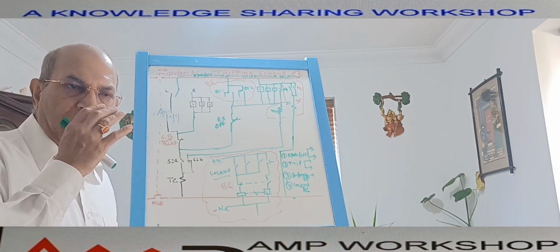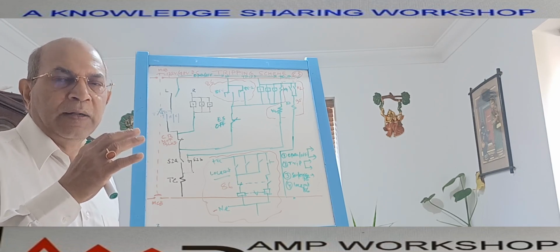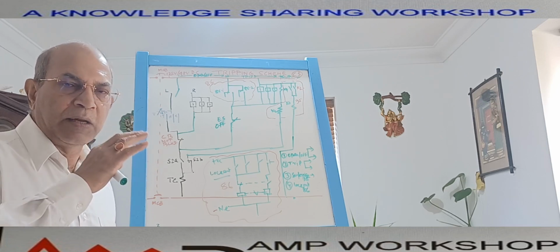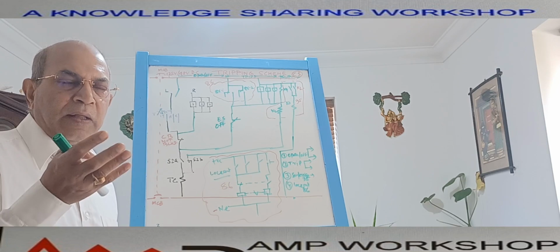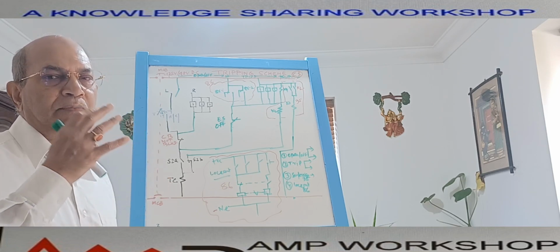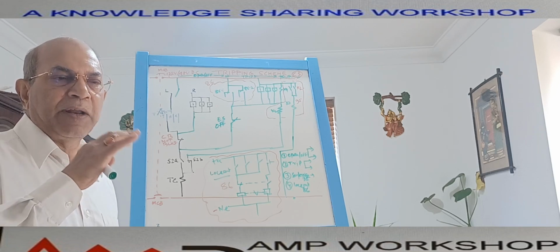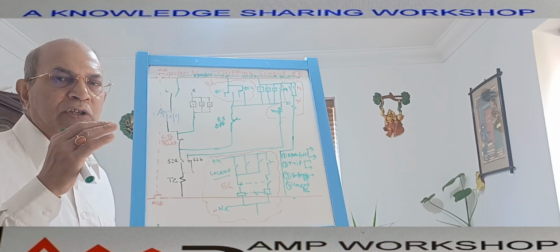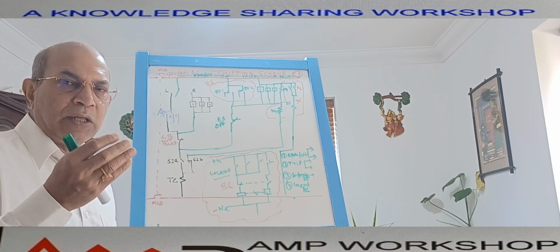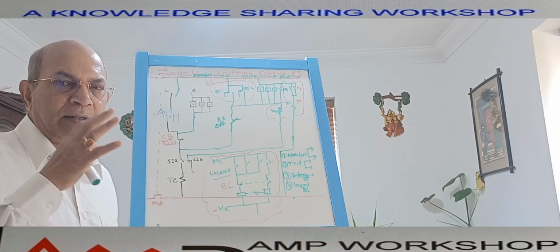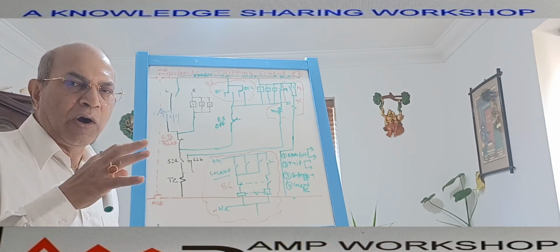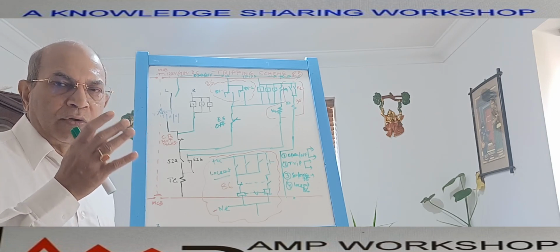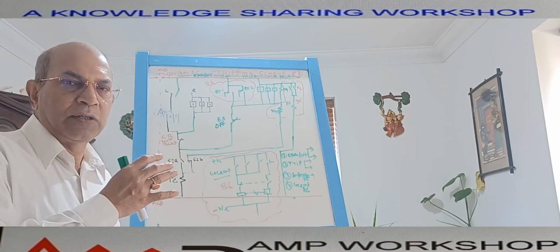When the fault current is flowing through the circuit and, due to failure of the trip coil or trip circuit, the breaker fails to operate, then the fault current will cause high temperature, which can cause a fire. That is why we need to supervise the tripping circuit or trip coil continuously, whether the circuit breaker is open or closed, so that if there is any abnormal condition in the tripping circuit, we can immediately monitor it.